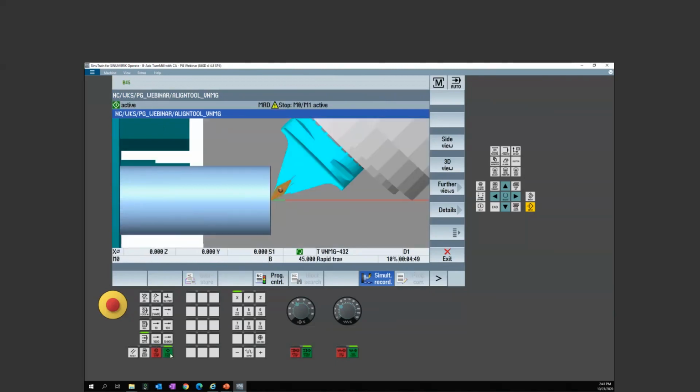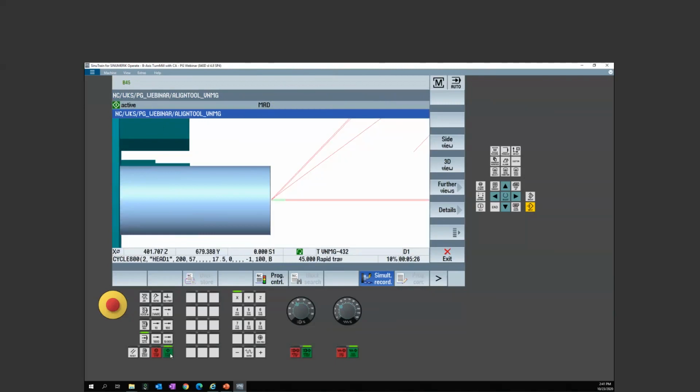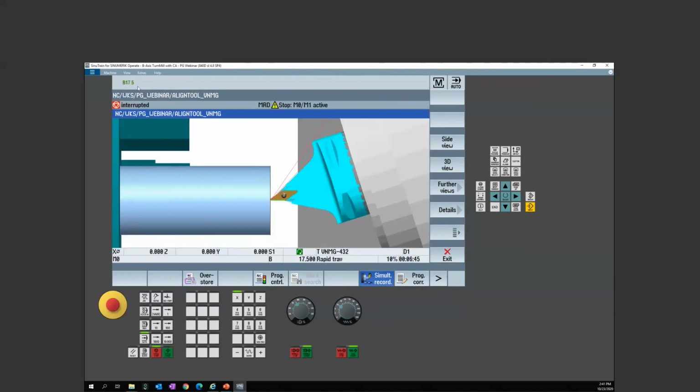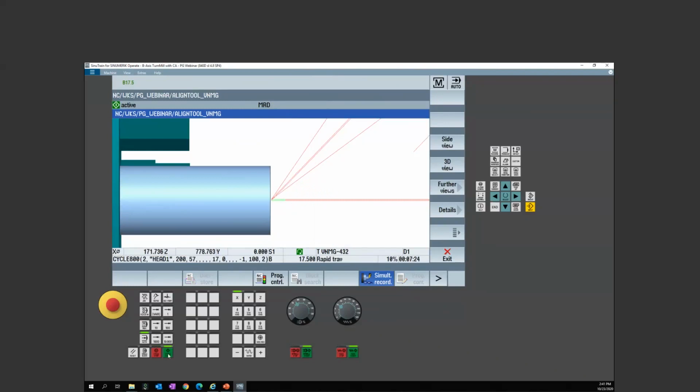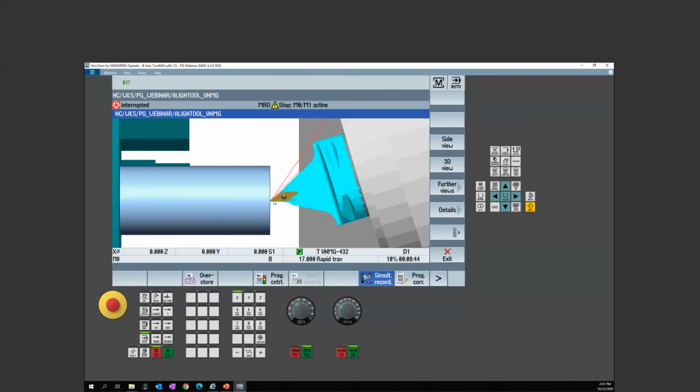Well, first I'll do my 45. Then we're going to come down to 17.5. So again, 35 divided by 2 is 17.5. So 0 plus gets me to 17.5, or 90 minus gets me to my other angle. And that's the range I can be within on this tool. The minute I go on either side of those numbers, greater than or less than that total angle swing, it's going to switch to the next cutting edge position.